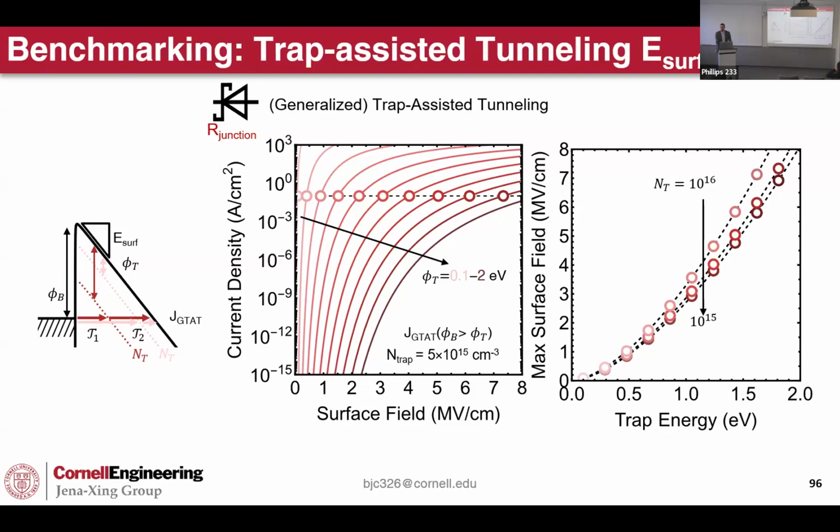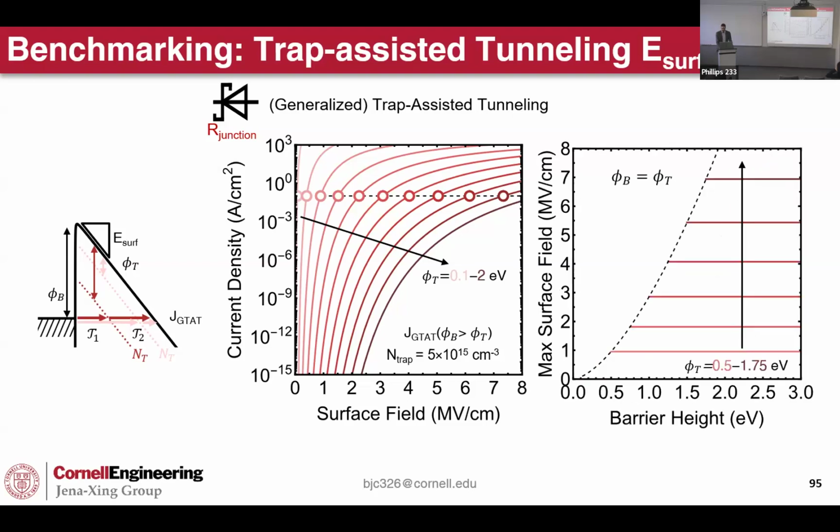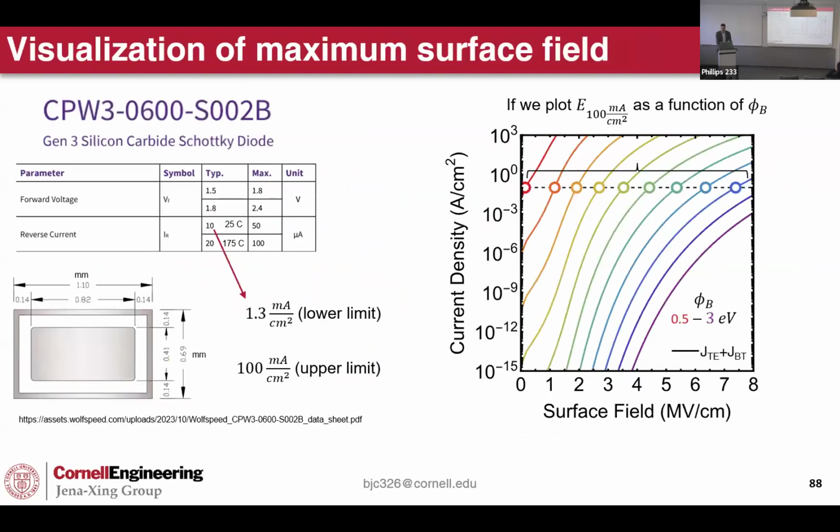Mostly, like you said, the motivation was to get a realistic picture of what's possible. Especially because in the research space, we tend to deal with milliamps per centimeter squared, but the eventual goal in these converters is to switch amps of current. So how close are our test structures to what we should actually observe when we scale this up?